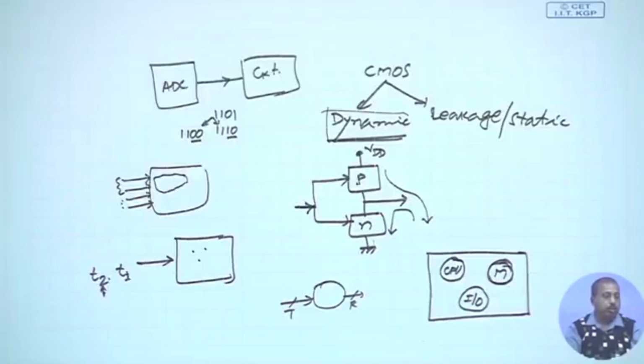Okay. So, since each vendor has given me a large set of test patterns, if I test these individual cores one after the other, it will take a lot of time. So, we try to do parallel testing. We test a number of cores together, but as a result, in normal operation maybe those cores are not going to act together. They are not going to act in parallel.